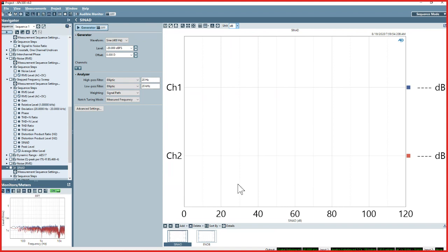So in particular, the delta sigma modulator we implement inside of APX for the PDM module only accepts, my memory is not quite perfect on this, but I believe it's some dB less than full scale as the maximum signal it will generate. So that's an issue. But I think to the core question, it's still a digital to analog or analog to digital converter, and these measurements remain relevant.